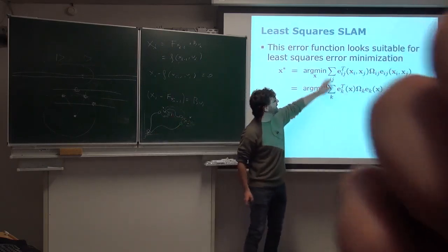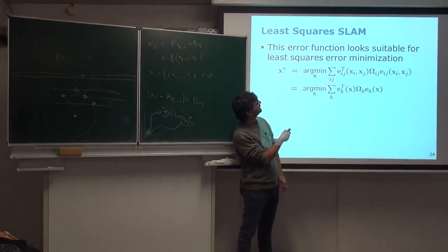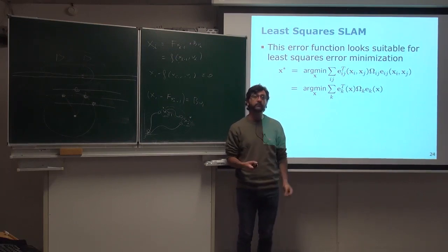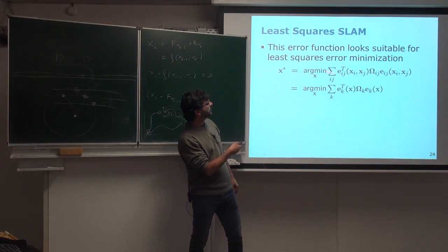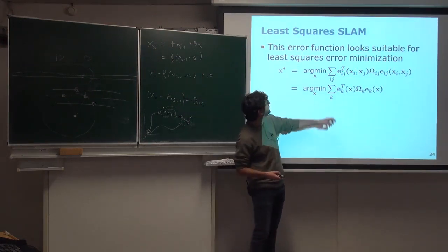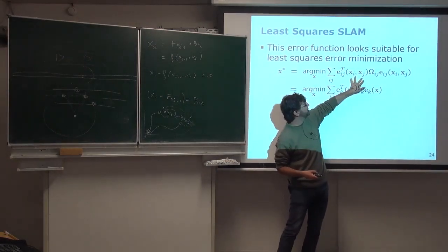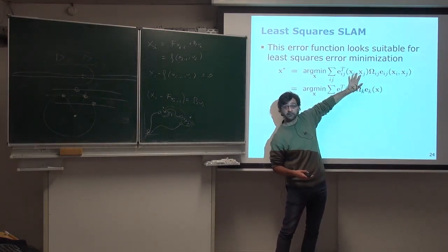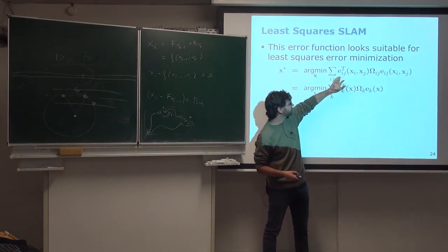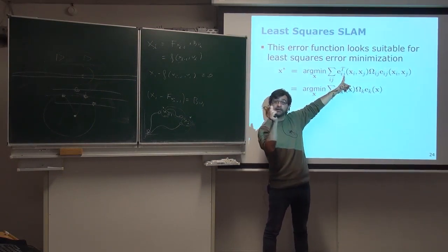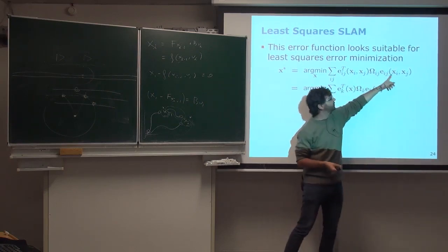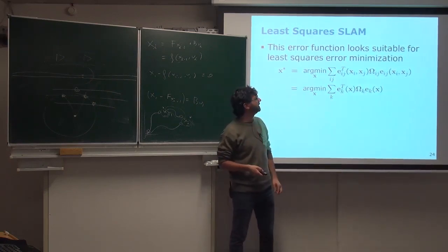If we now expand everything, we have that each ij where we have a measurement. So if you now look at how this can go into a least squares problem, again we can say these are subsets of our state space, xi and xj. We can write the error e_ij whenever we have an edge between node i and node j. And this is all the individual thing.